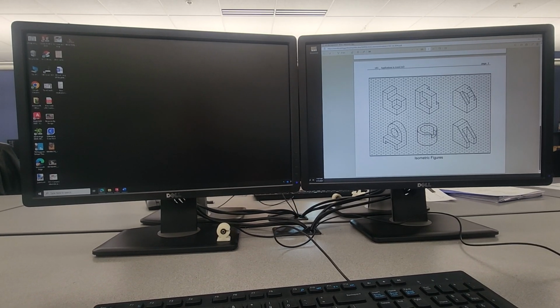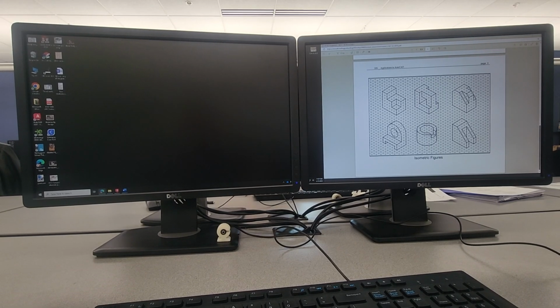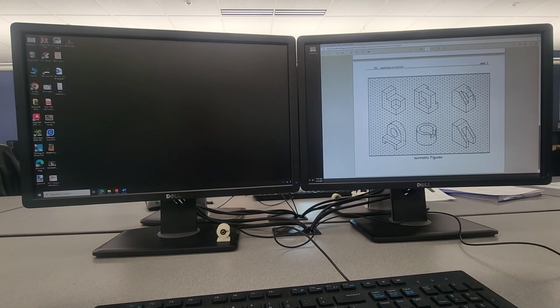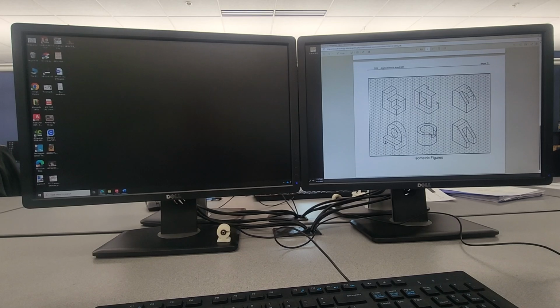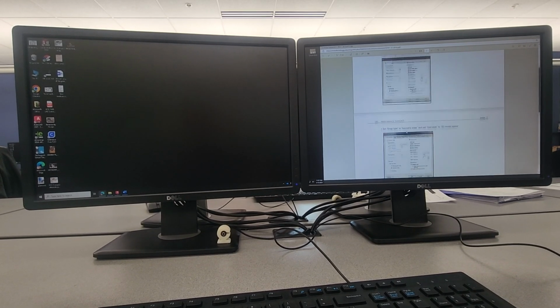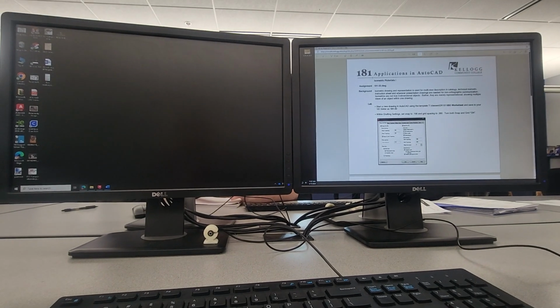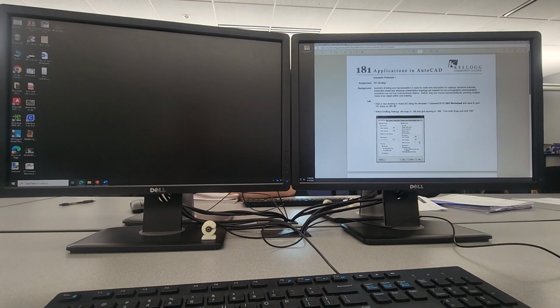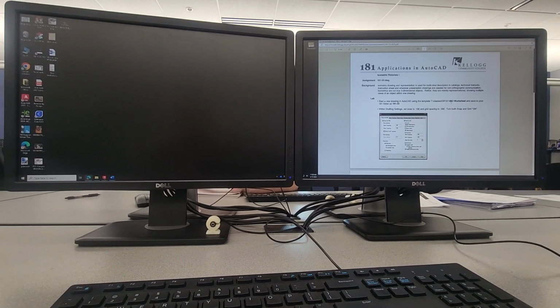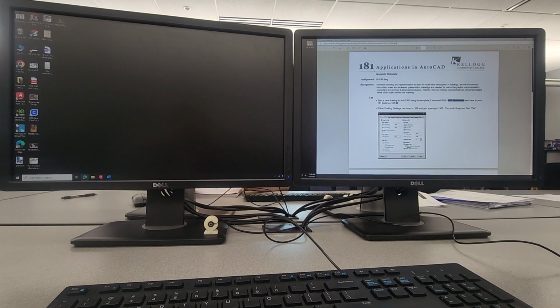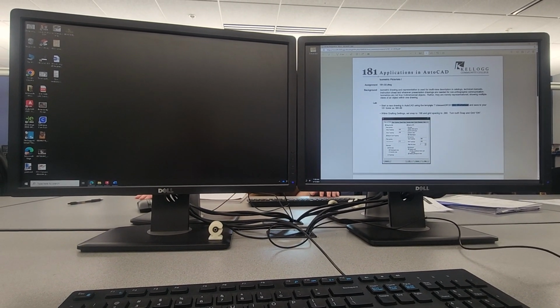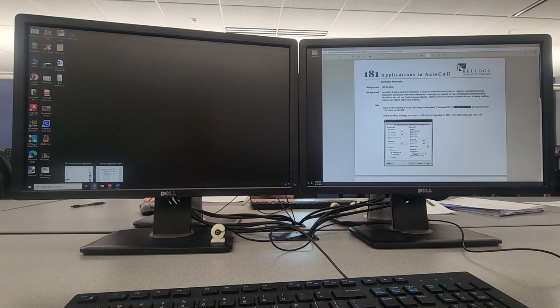So what we're going to be doing inside here today is I'm going to be teaching you the technique for doing isometric drawings like this in the field, in the world of AutoCAD. Now, it requires a little bit of setup, and it requires a special template. So what I'm going to do first of all, I'll put the instructions on here. We're going to start a new drawing, but we're going to be using a specific template to do this. Now, it's back on the T drive. That's the classes and support. But it's also available to you on the Moodle page.